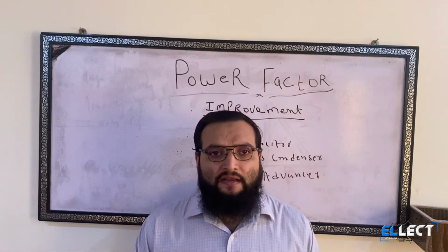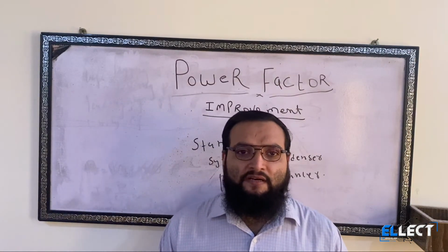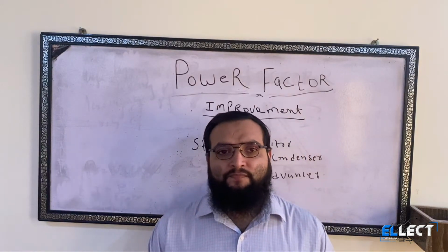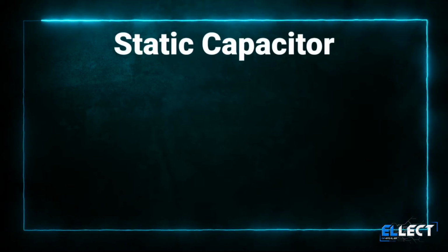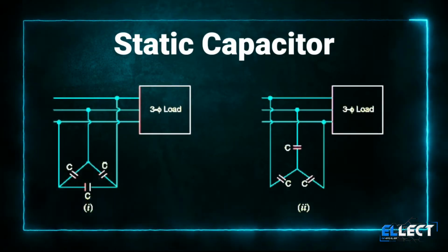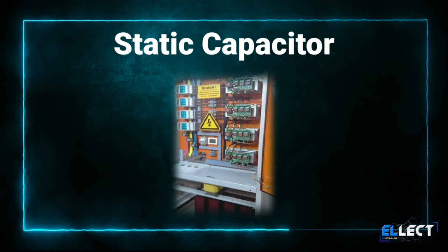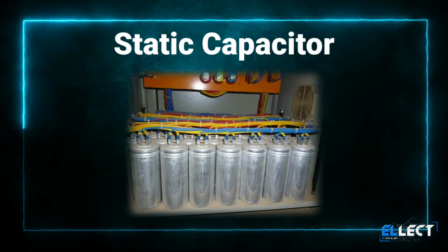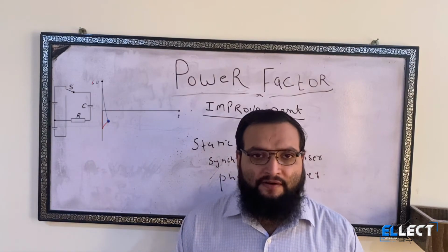There is a way designed by engineers and researchers: a static capacitor can cause the leading component of the current. As we know, whenever a capacitor is connected, it decreases the voltage and increases the current of the load, so whenever we connect the static capacitor, it neutralizes the lagging component of the current. The static capacitor is connected in parallel with the device which is working on low power factor.